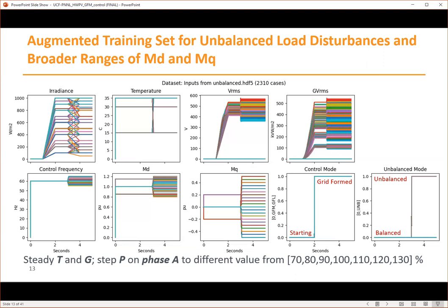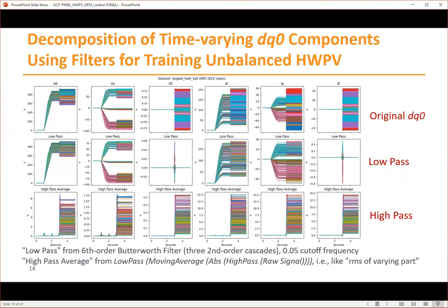We had trouble, just from the terminal quantities, knowing if the model was unbalanced. You have zero sequence voltage that could be detected, but it's not a very robust method. So we're going to leave that for later. Maybe a negative sequence relay or some other protection function would know if the model is going to be in unbalanced mode. Moving on to the next slide.